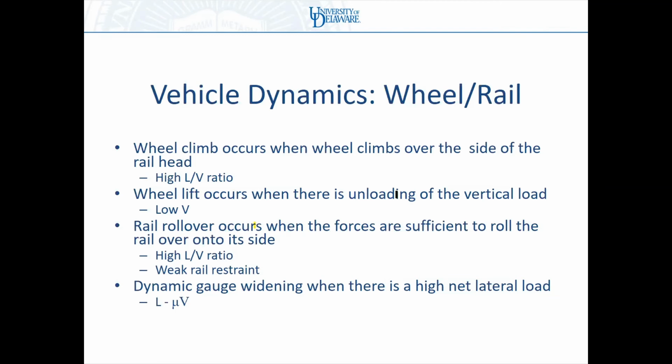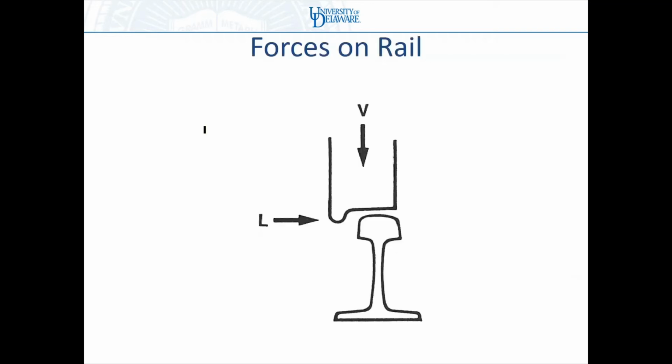All right, so just to go back and review, wheel climb. In fact, let me just show you wheel climb for a moment. So everybody remembers L over V, right? And if you remember, I also said in the European world, you'll sometimes see the term Y over Q. So for example, in that British report that I showed you of that derailment, they actually used Y over Q instead of L over V. You'll use those interchangeably. That's the ratio of lateral to vertical loads.